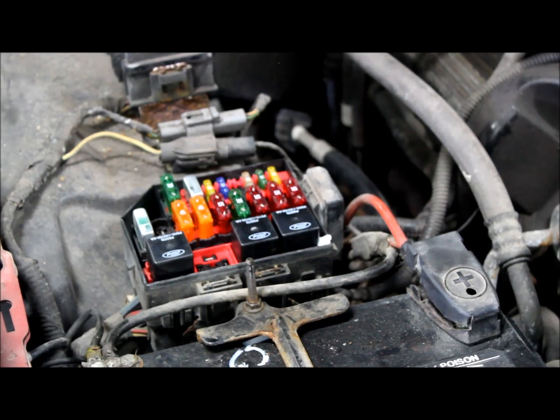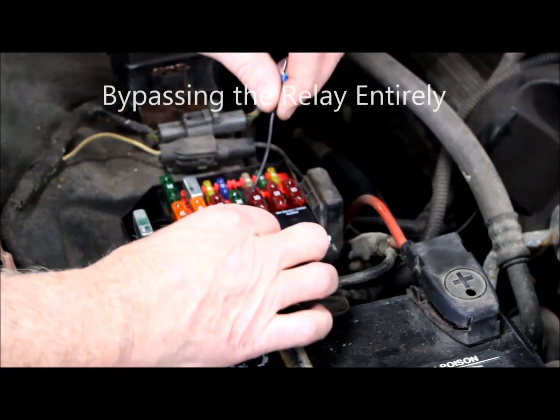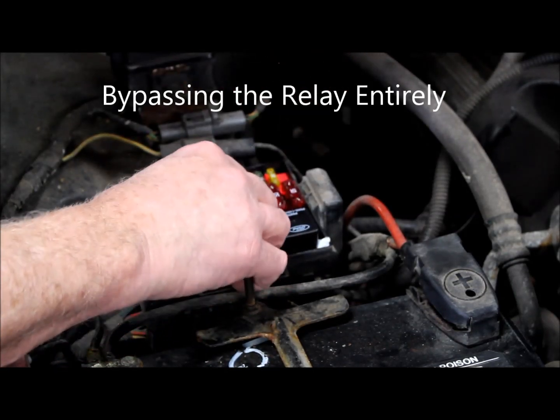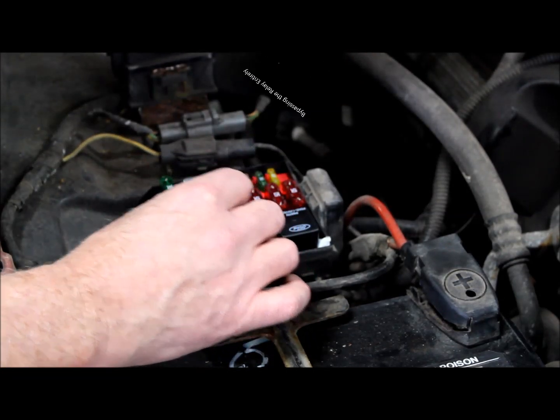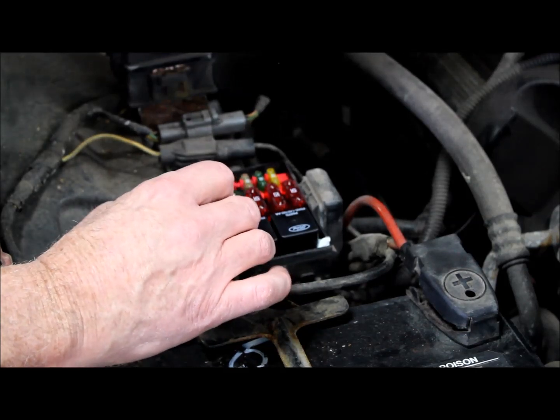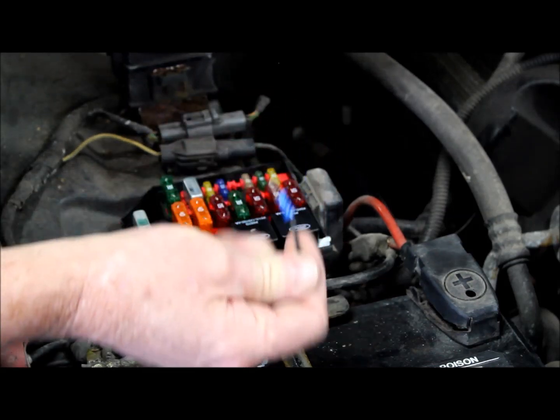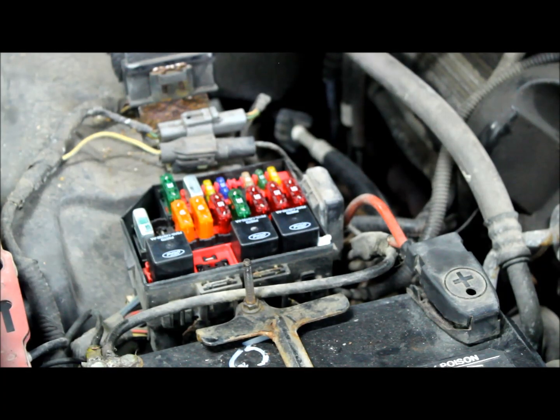So what I'm going to do is take a jumper wire, hook it into pin 30 and directly to pin 87. And I don't know if you can hear that, but I can hear the fan motor is running. So that tells me, the wire's getting a little warm too, that tells me that the fan motor is good and that the wiring to the fan motor and the ground is good.